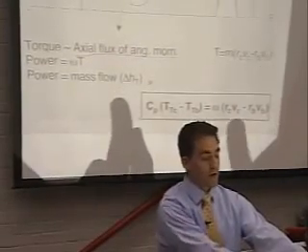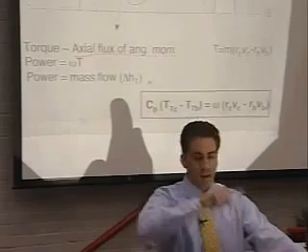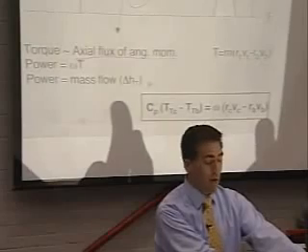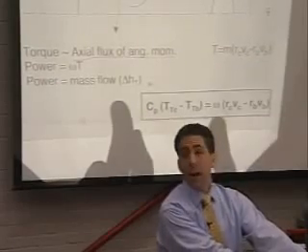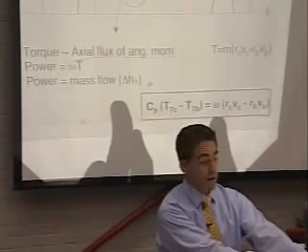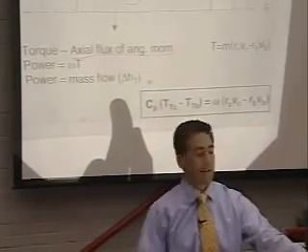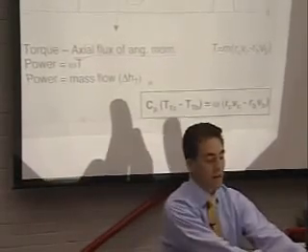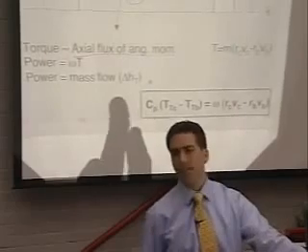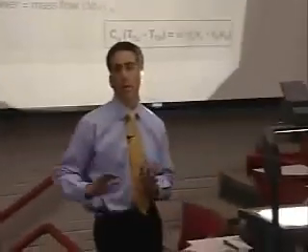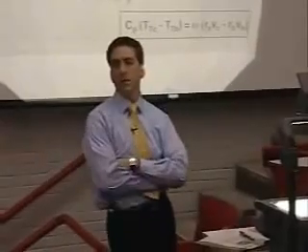If you change the velocity tangentially with a blade row, and you have that blade row moving, you get a change in the stagnation temperature. Right? That's the enthalpy, C sub P delta T total. And so that's what we got to last lecture. Are there questions about that before we go on to the blades themselves?